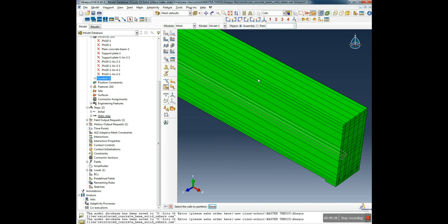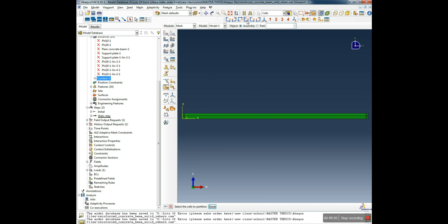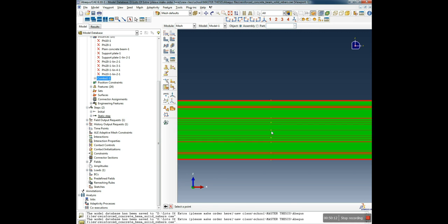And now we can go back to the general view and mesh it. But we will need to assign also some transversal partition planes. So we need this view, and we can select everything like this, click done, point and normal. Now there are so many elements and it starts going slowly. Click on this point here, create partition.